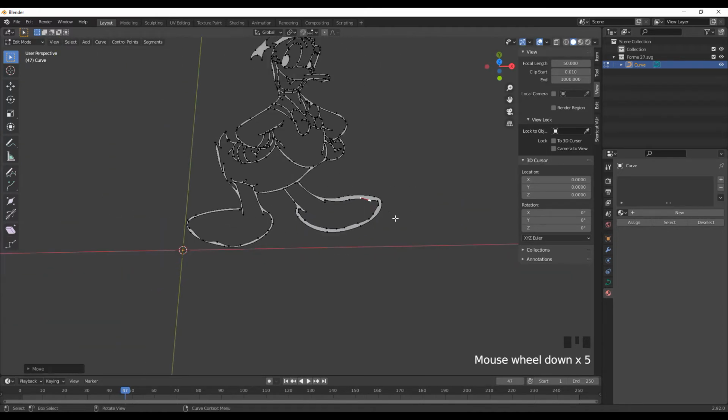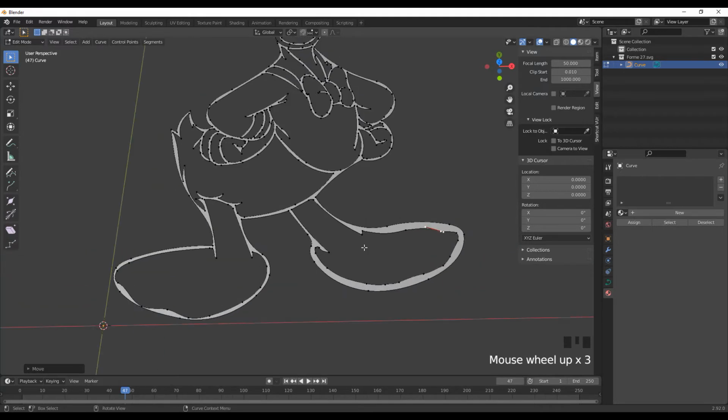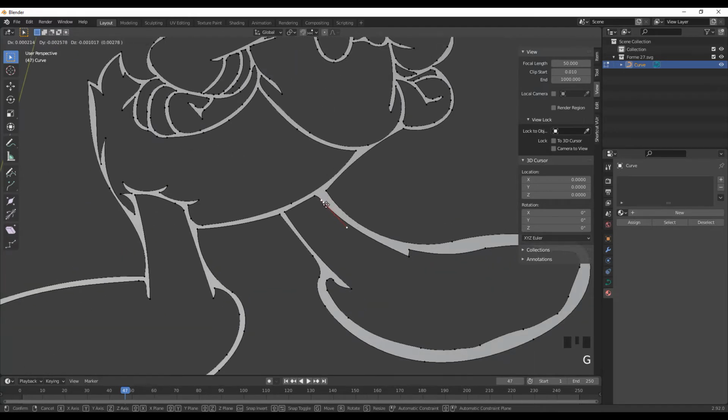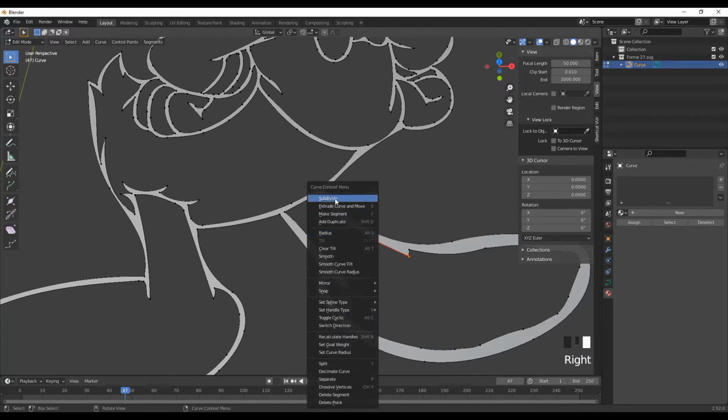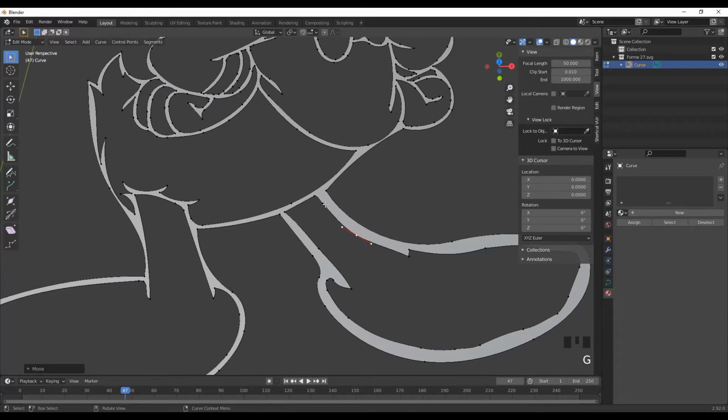So we will say that I respect the fact that it was a drawn object. Maybe we will work a little bit on the leg too. Okay, what you can do is select 2 points, right click, subdivide, and you can work even more on the object, even more on the curve. So it's quite decent to have something much better than you could expect in 3D Builder in part 1 and part 2, where when we work with software that is simpler, but it's more difficult to create a great thing. Blender is more sophisticated, we will say. I hope that it's a word in English.